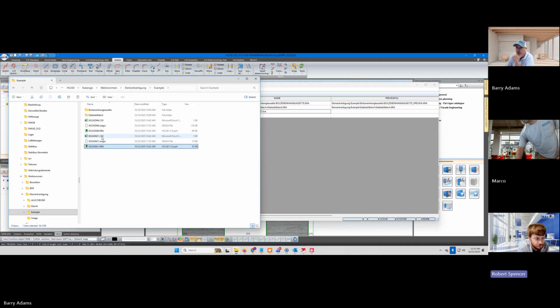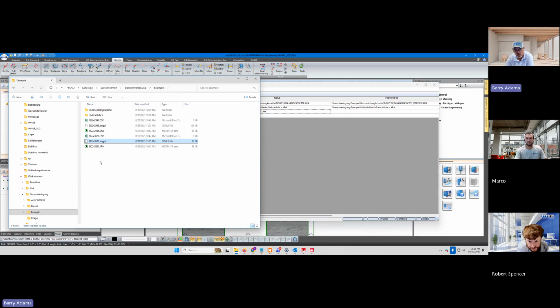The ISD GUI file is where that dialogue work that we did is saved. So notice that it's the identical part name to the KRA. So if you make them identical, you don't need an entry in your dialogue column, okay? If your part name and your GUI file have the same name, minus the extension, of course, then you don't need a table entry there.